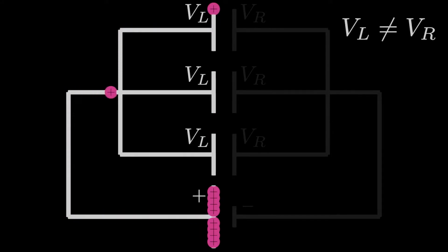On the screen here, the charge transfer looks really slow, but in reality this happens almost instantaneously. Charge continues to flow until all of the left plates and the positive terminal of the battery are at the same electric potential, because the entire left side is just one conductor now, and that one conductor has to be at the same potential everywhere once charge is done moving.